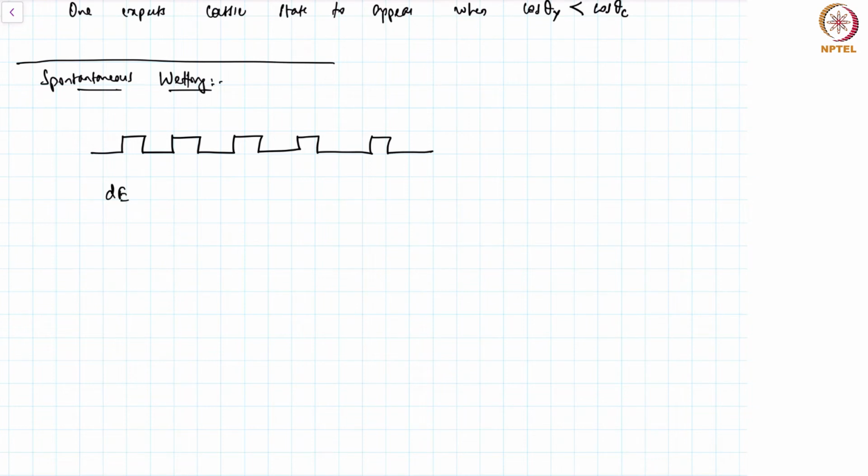When the fluid first travels by a distance of dx, in this case it will be gamma SL minus gamma S times (r minus phi s) dx plus gamma times (1 minus phi s) dx. So what really has happened is the liquid has basically traveled all along the surface, and it's a case where the apparent contact angle has basically gone to 0.